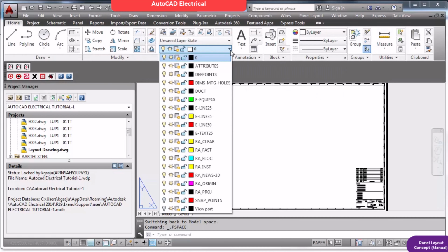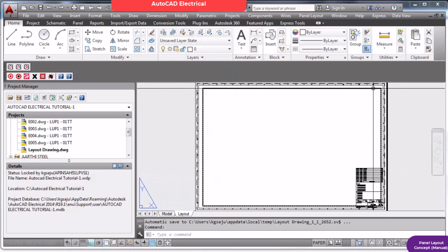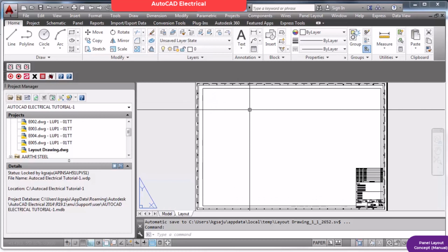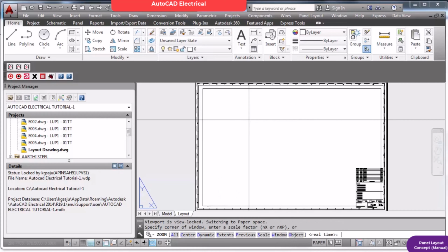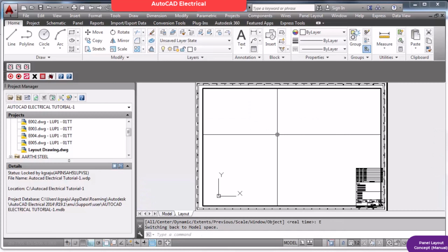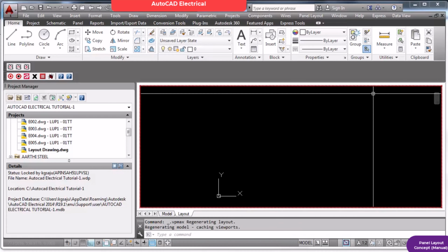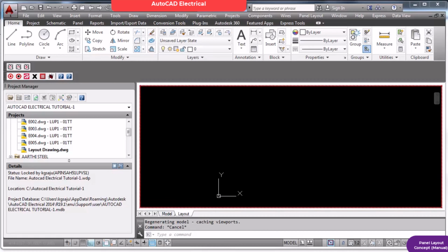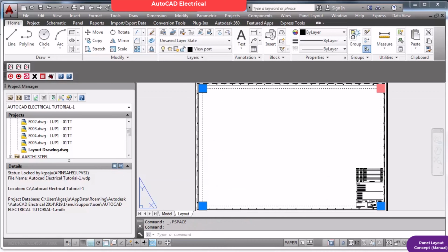still now I cannot see anything, because now I am coming out. Now the viewport has gone. I don't know where the viewport is. So probably the layer viewport is off now. Yeah, this layer is now off. Now I am going to turn on this particular layer. Now you can see the viewport, this rectangle. This is called a viewport. Now I'm going inside this. I'm giving the command. All these commands will work here as well. Zoom extend. Still my drawing is not appearing here.